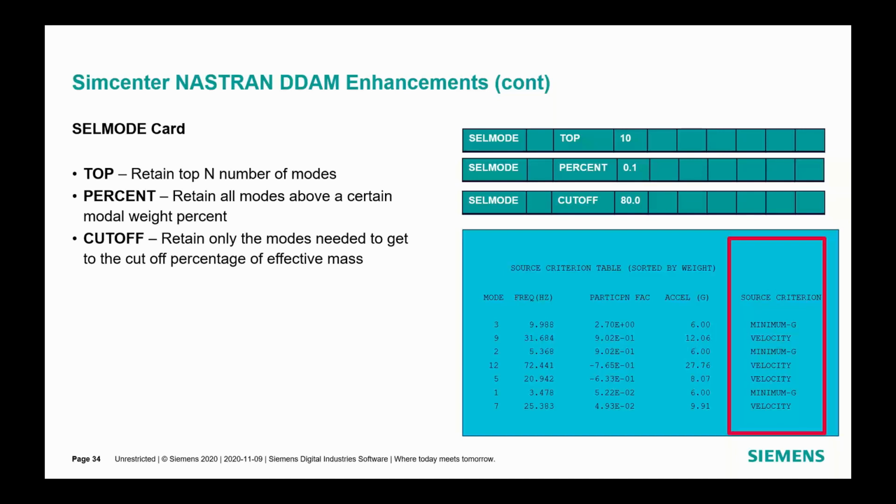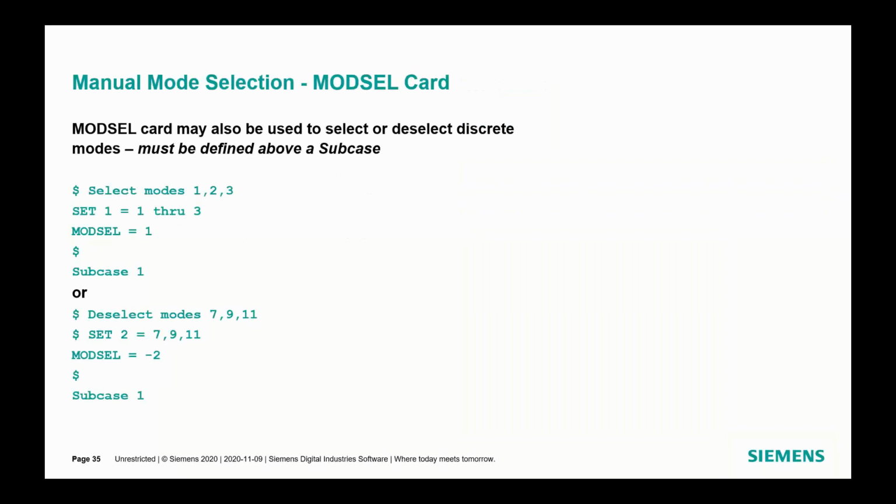And as I mentioned to you, there is a bug at this point, and the workaround is to rename the ddam.f21 file to ddam.inpl. Like I said, that was a bug that just turned up recently.